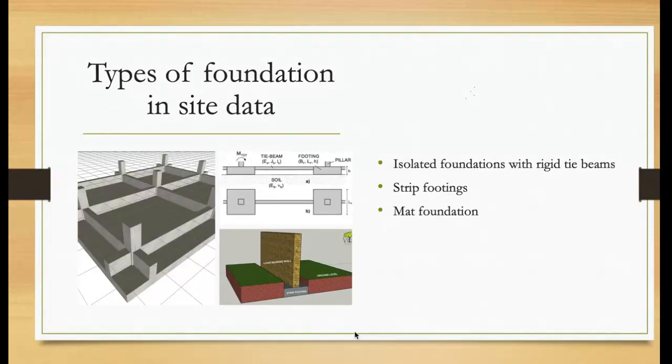And the design of the foundation, like the depth, depends on the shear that will apply on the foundation, and the steel that we will provide in the foundation will depend on the bending moment.